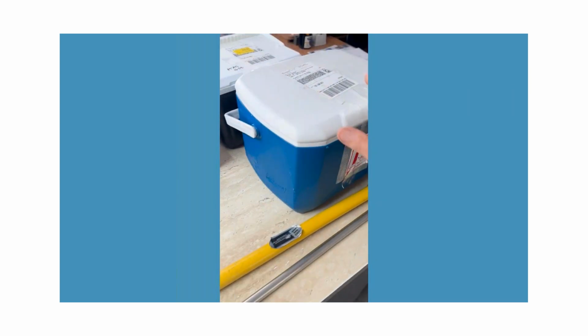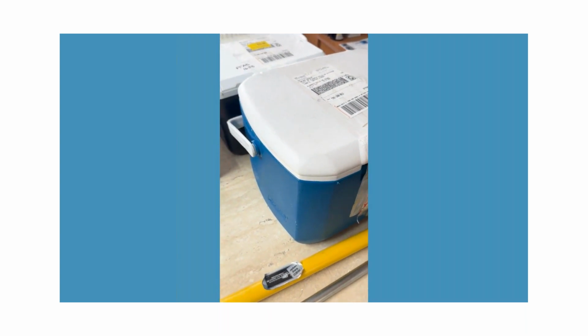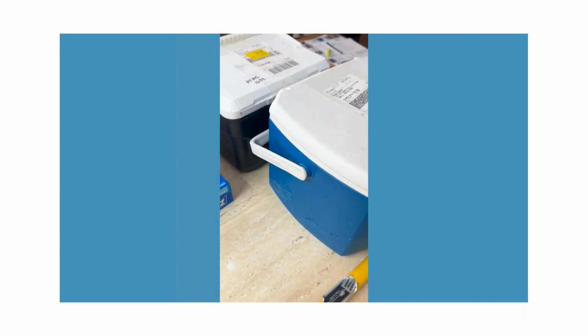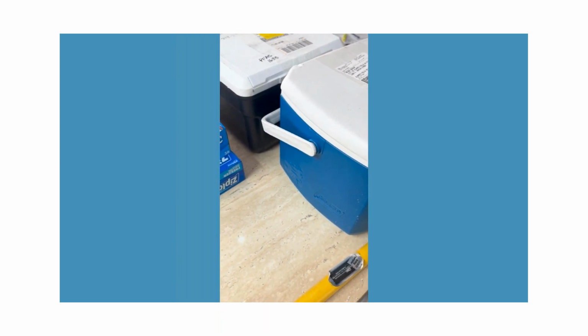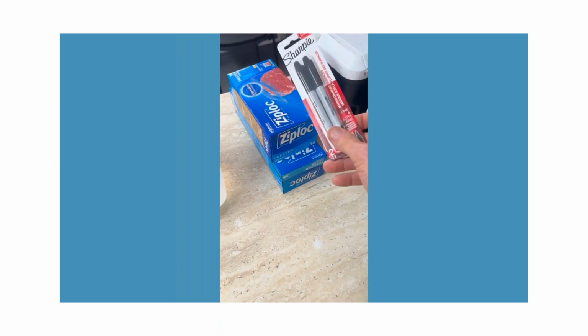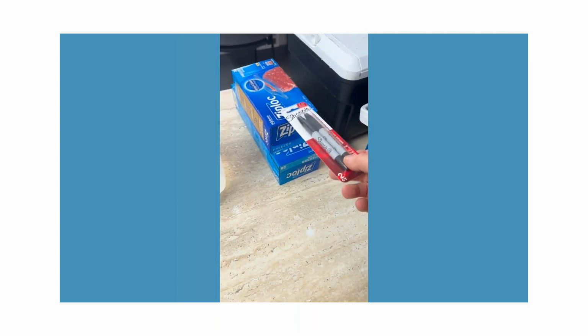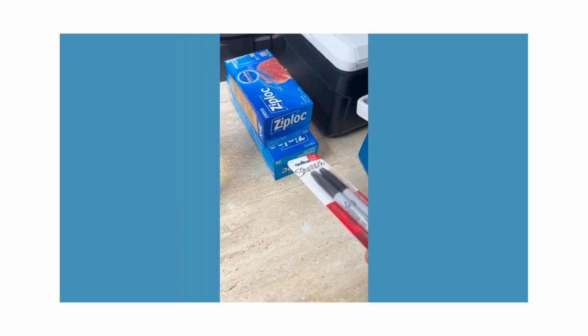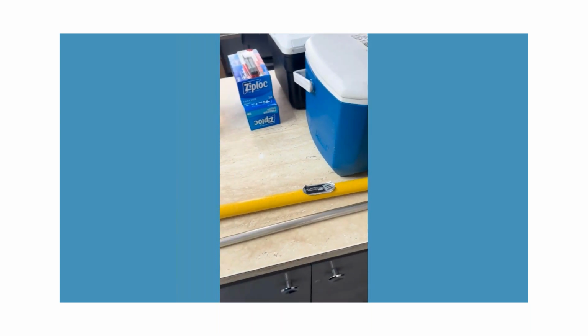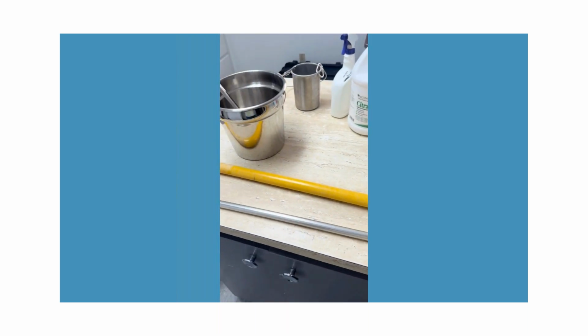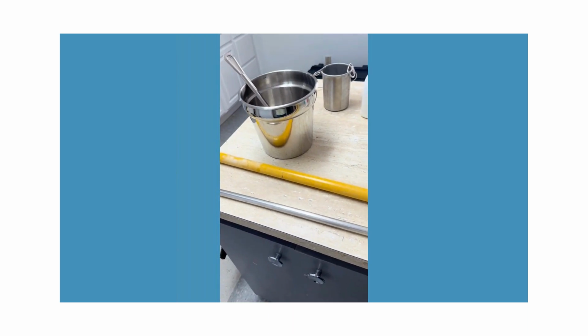I have my sample bottles that were prepared at the lab. I normally do not open these coolers until the day of sampling, and then I fill out the chain of custody forms and the bottle labels using a Sharpie fine point or ultra fine point pen. I also make sure I have plenty of Ziploc bags in case I need to double bag the sample bottles or even the ice. So we're going to get things cleaned up, and we'll see out in the field when we start sampling. So we got our chain of custody filled out.